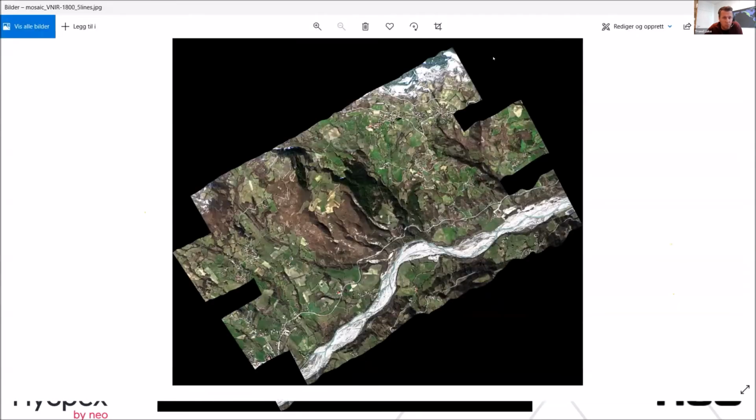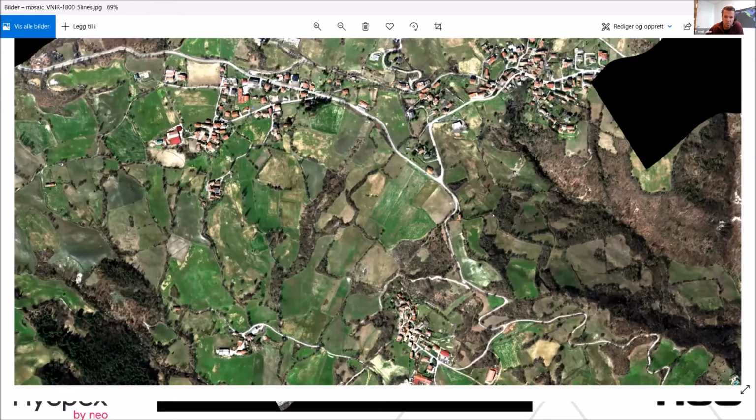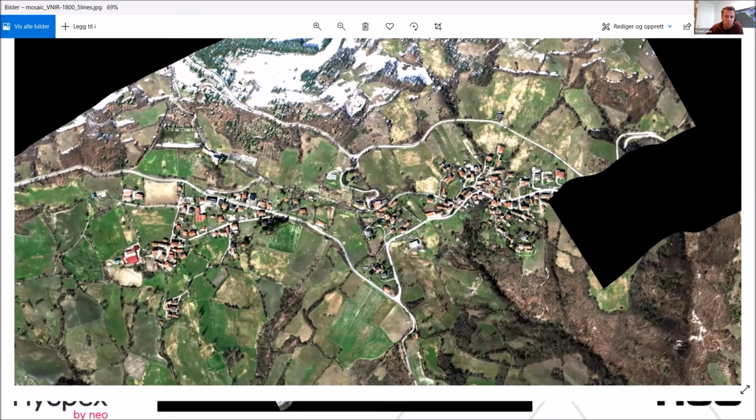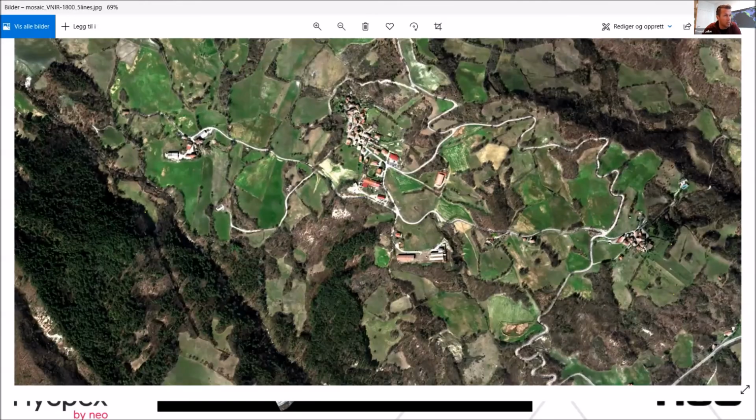When you have full control of geometry, your sensor model, your elevation model, your boresight, your height reference, everything we're going to talk about now, you can get auto-rectified images where you merge together 100 flight lines over a big area without any GCPs on the ground, and you cannot see the stitching between the flight lines because of the accuracy you have in your boresight, in your DSM, the stability of your system, and so on.